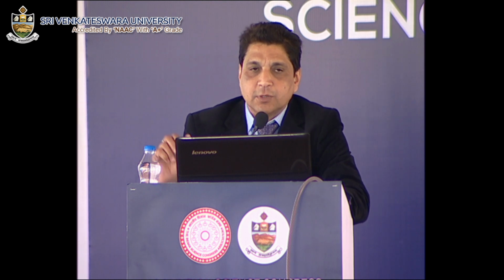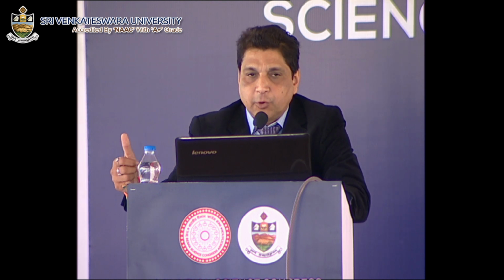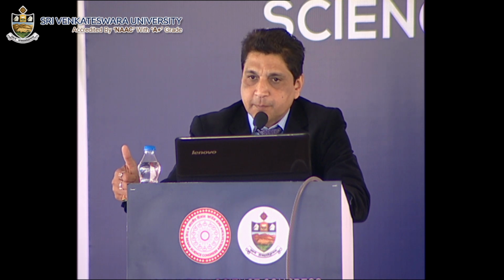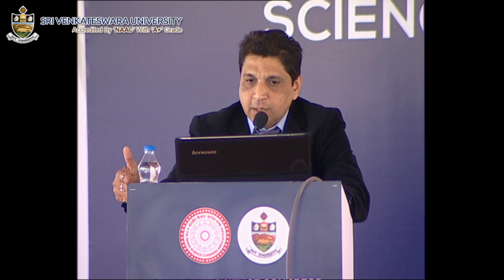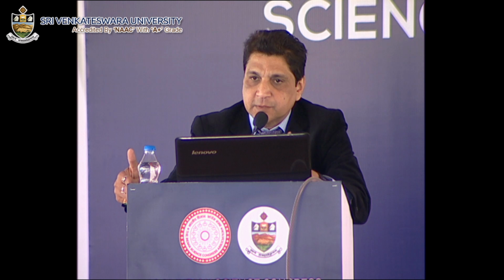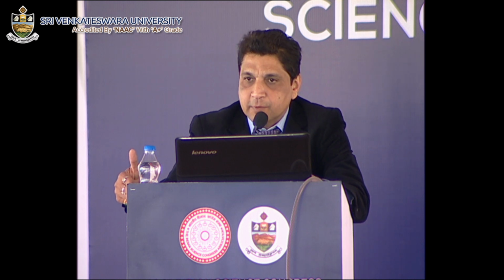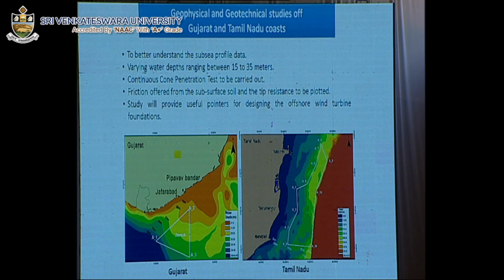And this will also help us in designing the substructure foundations particularly, because the parameters, the soil resistance and the tip resistance which is offered to the cone, will be measured continuously, and this can give us a useful pointer for designing the various kinds of foundations which are required for wind turbines to carry such huge loads.